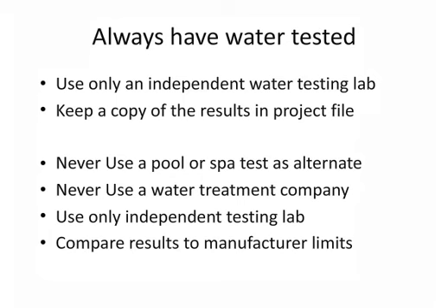Always keep a copy of those independent laboratory test results. I always attach those to a copy out of the manufacturer's handbook of their acceptable water standards for their heat pump, and I put that in my job file for several reasons. First of all, you want to make sure it's an independent testing lab because they have no skin in the game. In other words, you're not influencing them. You paid for this. This is what they do. It's on their letterhead or their report, and it's dated, and all of the results are right there. So you have done your homework, and you've pretty much covered yourself.